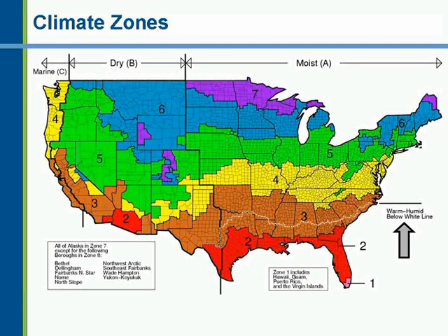in the southeastern part of the U.S. That white line defines what's known as the warm, humid counties. And those counties are based on ASHRAE's definition of a warm, humid climate. They are different from the moisture regimes. For the most part, they are not used in the code yet. The thing is there primarily to accommodate things like economizers in the commercial side of the code where humidity considerations are important. The only place that line is used in the residential code is with regard to basement requirements in Zone 3, where the warm, humid portions of Zone 3 do not have any requirement for basement insulation.